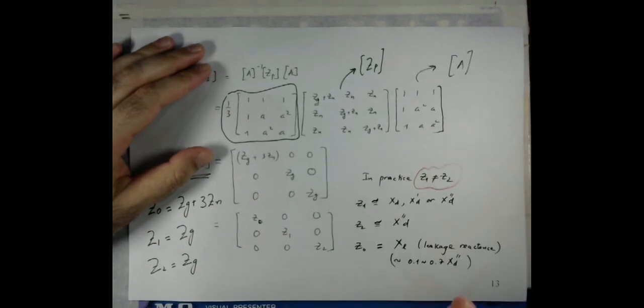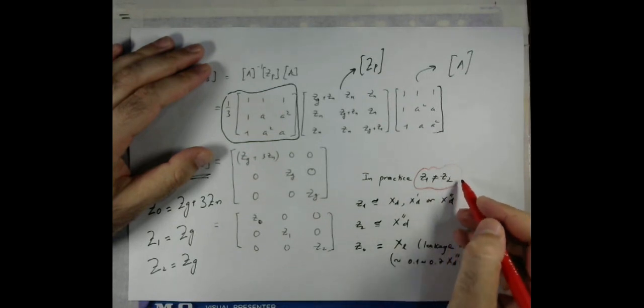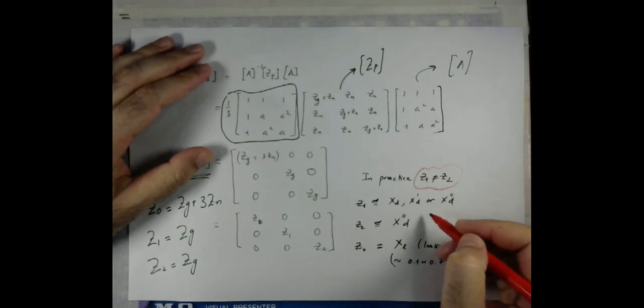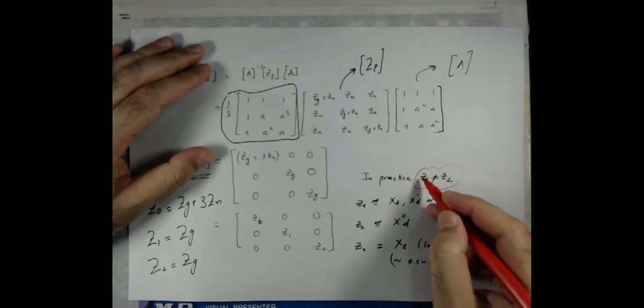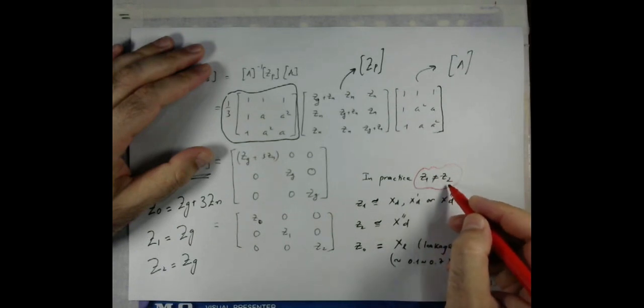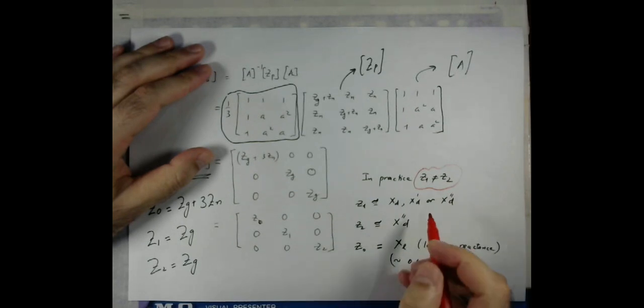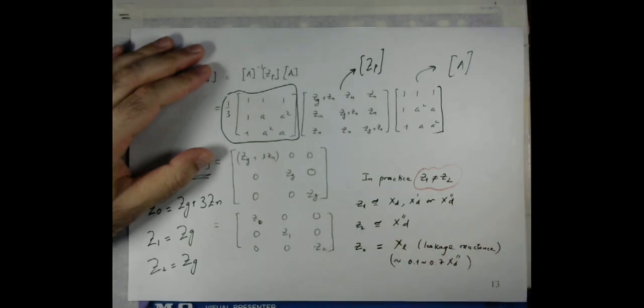Maybe observations are made, or measurements, or deep studies may be made where it has been found that Z1 is not equal to Z2, meaning to say that the positive sequence impedance is not equal to the negative sequence impedance. And usually in the circuits that we will solve later on in another lecture, not in this lecture, when I will solve, let's say, single line to ground faults, we will analyze that case.